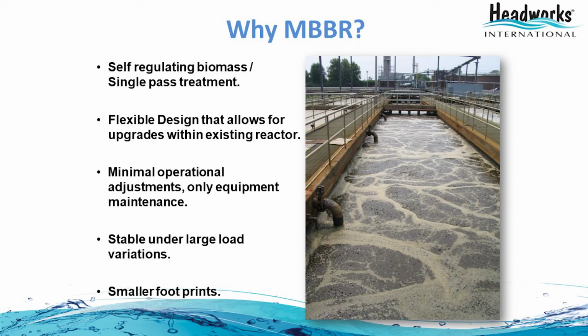When you have a high load variation, the biofilm automatically shrinks and grows. So it's very stable under large load variations. And the most important thing is the very small footprint. If you have experience with activated sludge plants, we can shrink the footprint by a factor of 4.